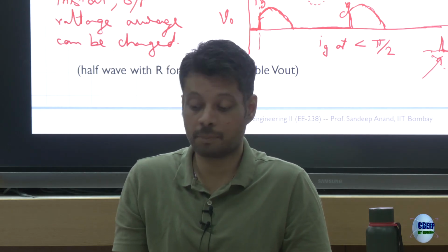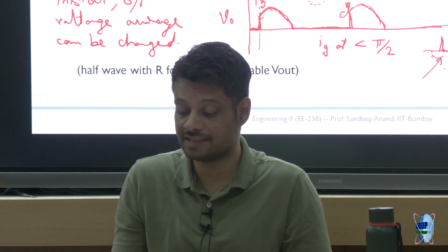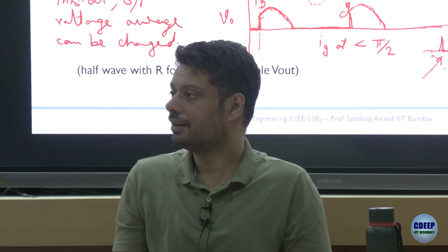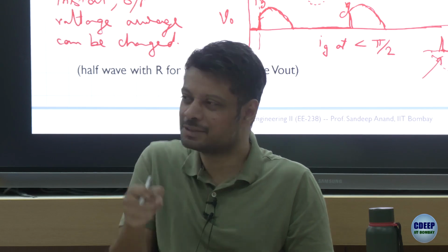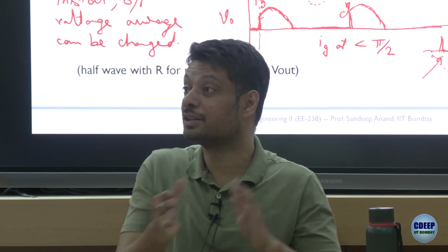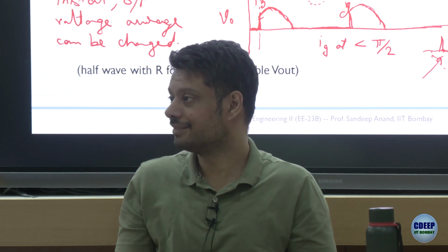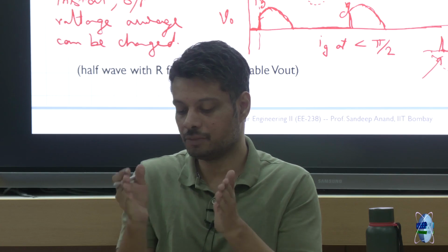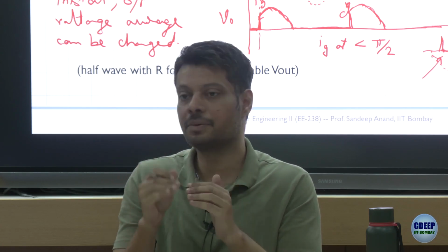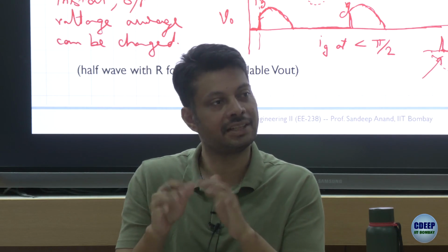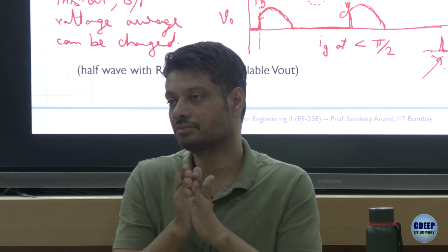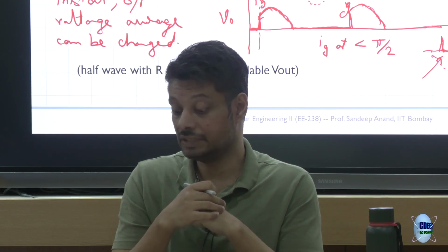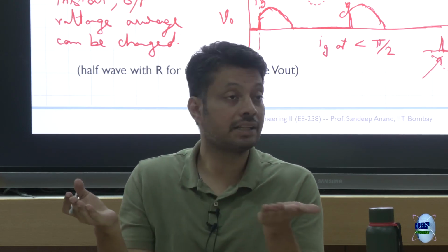Okay, so she is asking what happens if you give the pulse just before the rising cycle. Now, just before is very tricky, right? If you give it just before, it will start, but if you give it just before, it will not start. You got the answer, right? Basically, you should have both Ig positive and Vak positive at that moment, then it will start. Yeah, so if you can do that, that's a good choice, right?